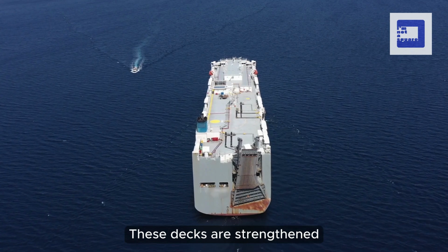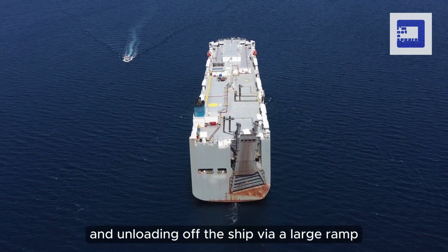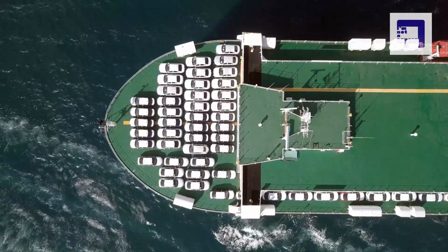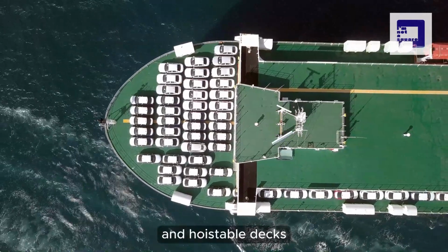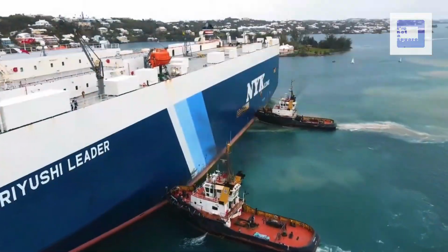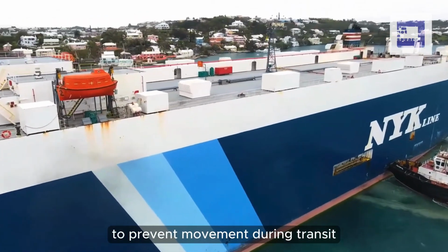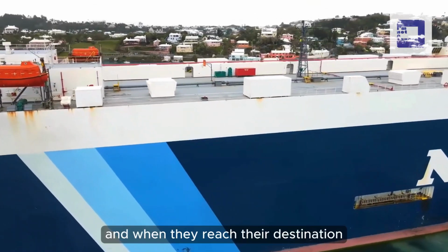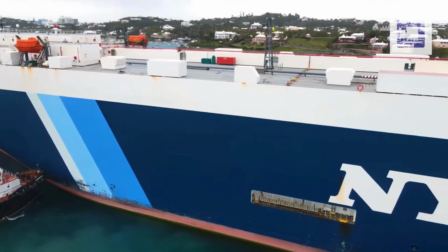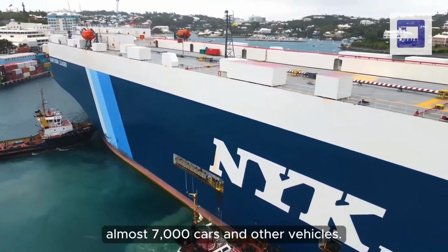These decks are strengthened to allow loading of vehicles of varying shapes and sizes and unloading off the ship via a large ramp at the stern. Car carriers are equipped with ramps and hoistable decks that allow vehicles to drive directly onto the ship. Once on board, the vehicles are securely fastened to the deck to prevent movement during transit, and when they reach their destination, the vehicles are simply driven off the ship. Car carriers have the capacity to transport almost 7,000 cars and other vehicles.